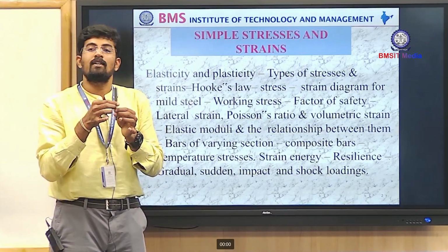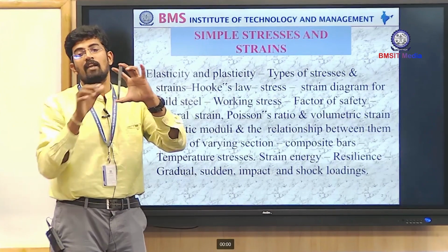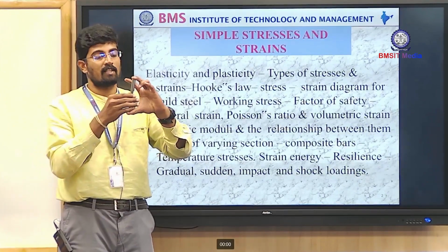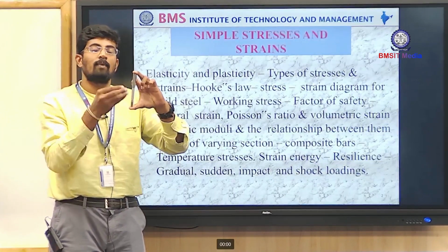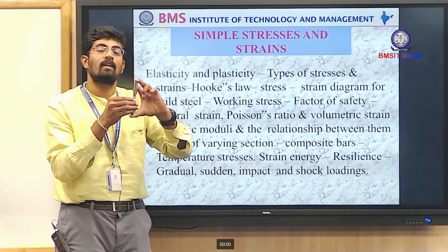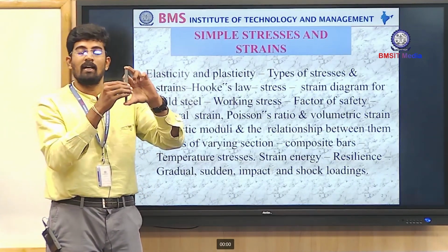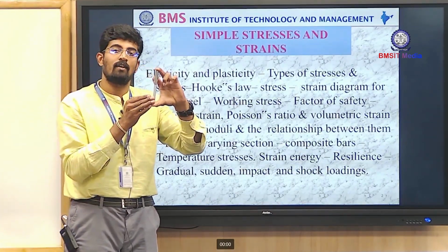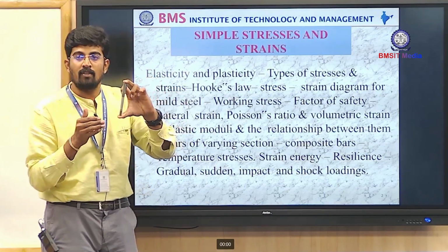There is a term called factor of safety. I need to be very safe; we should all be on the safer side. So I'll consider some factor of safety and design it for that particular load. I won't take 100 kilonewton and design; I will reduce that by a small portion. So how much portion should I reduce? There are some